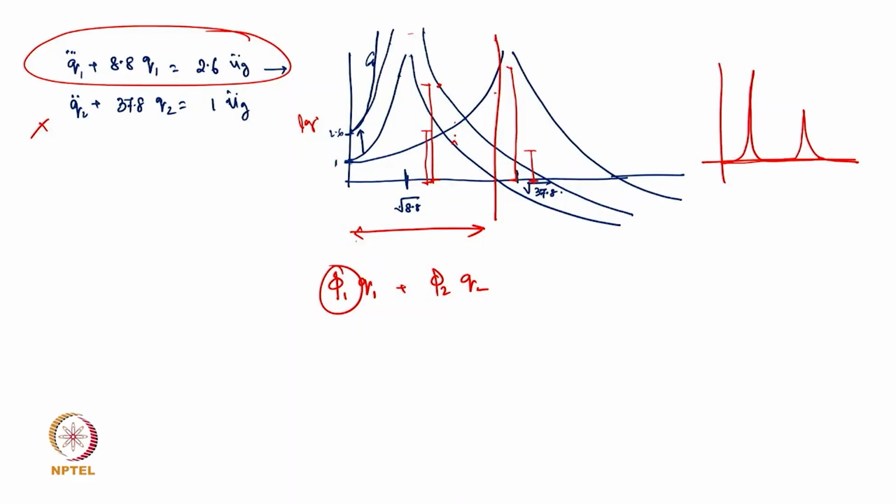But that is the frequency of the bare frame, not the infilled wall. For the infilled wall, the time period, I think, will be lesser. It will become mostly stiffer. Although you are adding some masses, the joint stiffness and all those things will be increased. So that way the things happen.